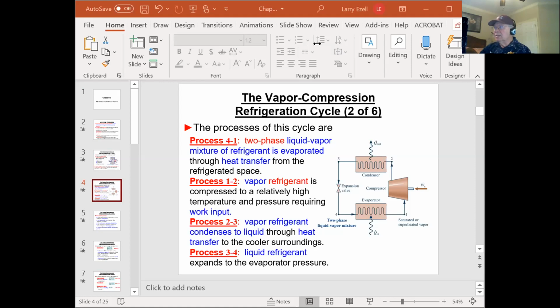All right, let's go to the English units. So we're going to deal with R134a. Let's look at page 994. If I want to design an HVAC system to give me about a 60-degree coil temperature, what pressure do I choose?